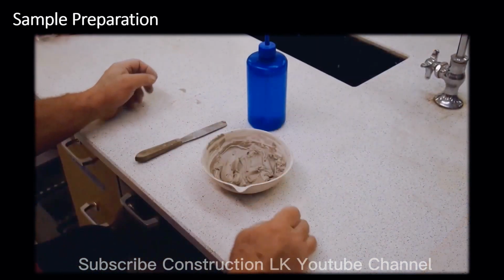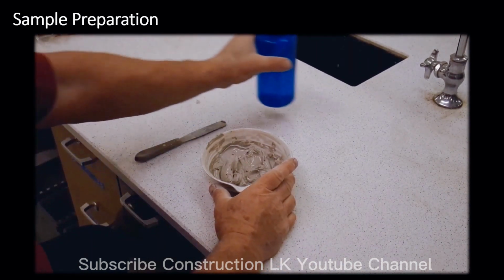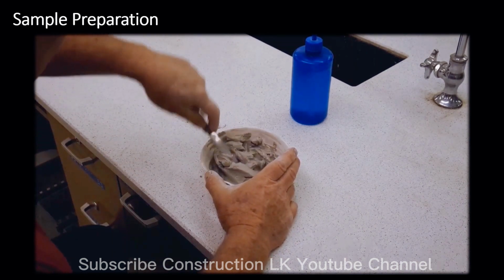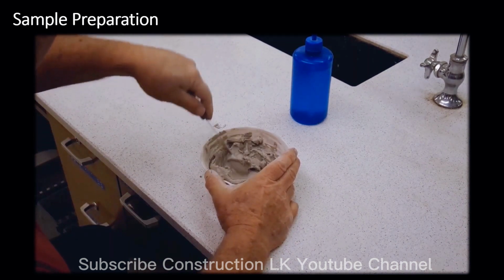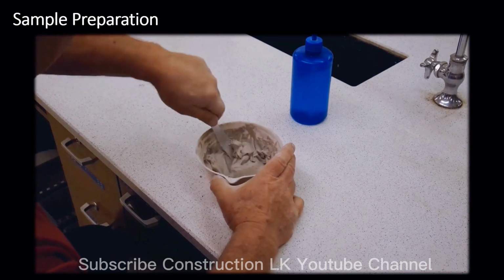Soil sample of about 250 grams finer than 0.425 mm, obtained through the above procedure, should then be thoroughly mixed using a spatula. Mixed soil should then be returned to the mixing dish, covered to prevent loss of moisture and allowed to stand for at least 16 hours.